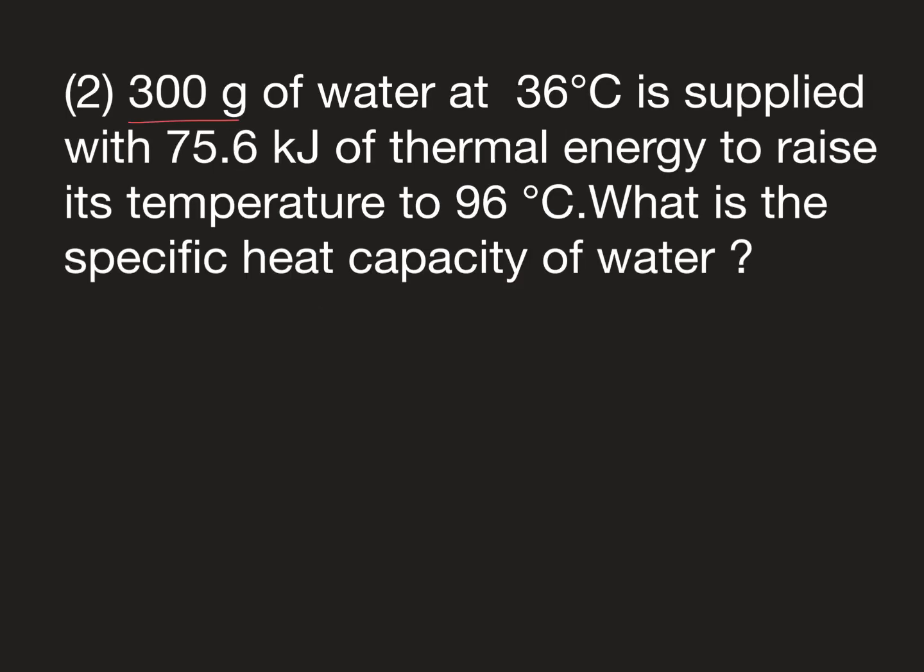300 grams of water at 36 degrees Celsius is supplied with 75.6 kilojoules of thermal energy to raise its temperature to 96 degrees Celsius. What is the specific heat capacity of water? Solution.